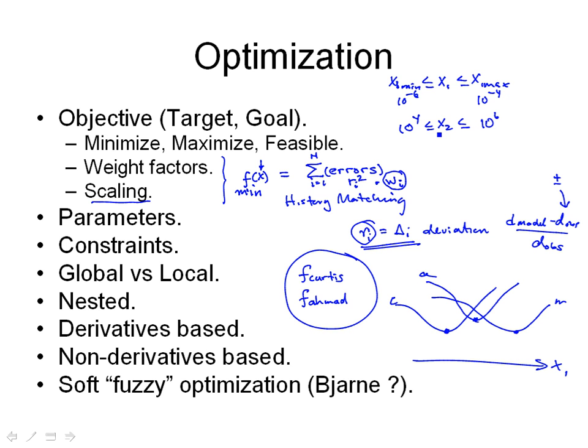If you go to Solver with this kind of problem, I don't care how simple the function is, if it's nonlinear, and you try to solve this, it's probably not going to find the optimal x1 and x2. Unless you turn on the little option called scaling. I think that's what it's called. Okay? And what the scaling does, it's not default.